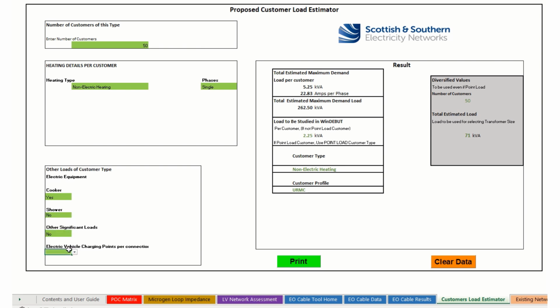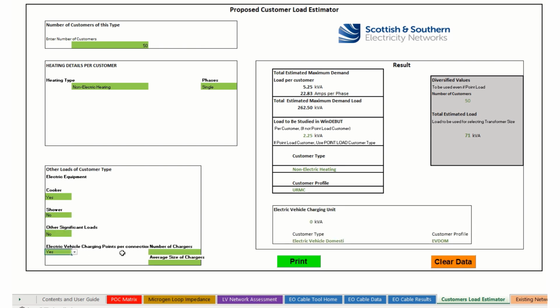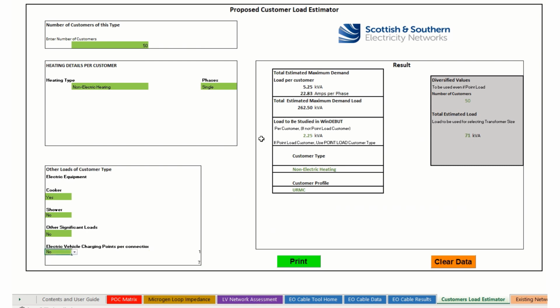You can avoid resetting, for example, if half the site has EV chargers and the other half doesn't, you would run this twice: for half we'd remove the EV chargers and for half we'd have the EV chargers, which is what I'm currently doing in the example that I'm showing here. So you can add these values to get a diversity load of 300 once you get there.